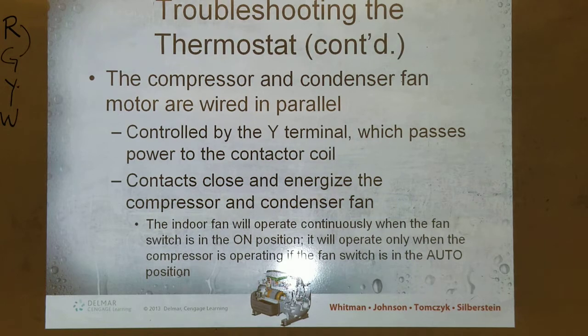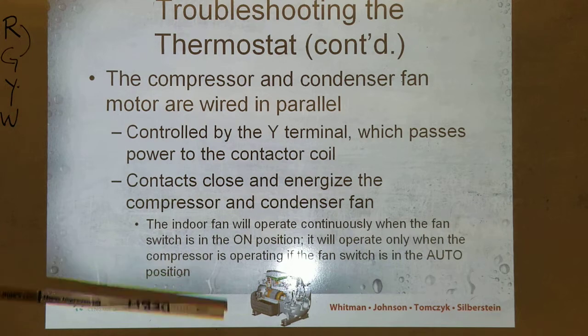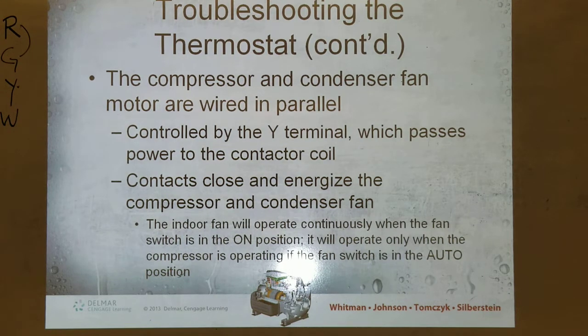Okay, so the compressor and condenser fan motor are wired in parallel, we got that. Controlled by the Y terminal. Right? The indoor fan, you guys already know this. Anybody have a thermostat at home? I have one of those old school ones. So we know when the fan is in the on position, the fan just never shuts off. That's all it's saying.